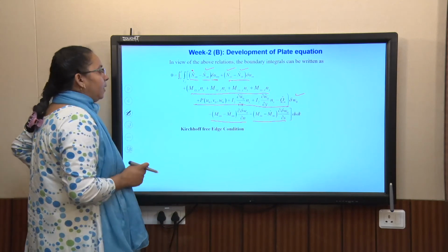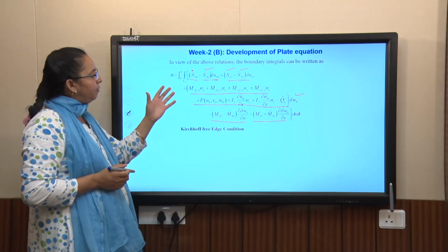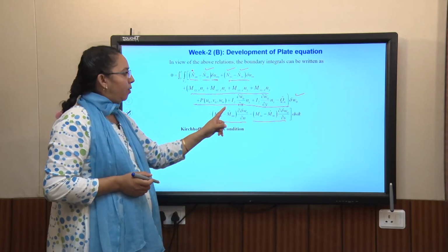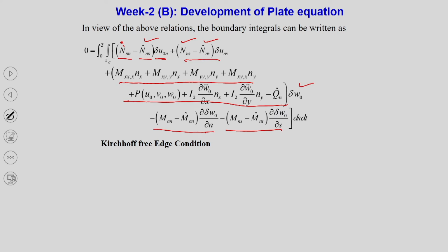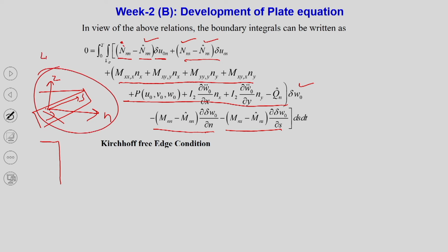So, here I would like to point out that till here you find that 1, 2, 3, 4, 5, there are 5 boundary conditions that need to be specified. But on an edge of a plate, how many variables can you specify? Along normal, along shear, along the z direction, and one is the slope. So, basically you can specify a maximum of 4 variables at one edge, one slope and 3 basic variables. They may be mixed; if you talk about all displacements u, v, w and then w comma x, that you can specify.